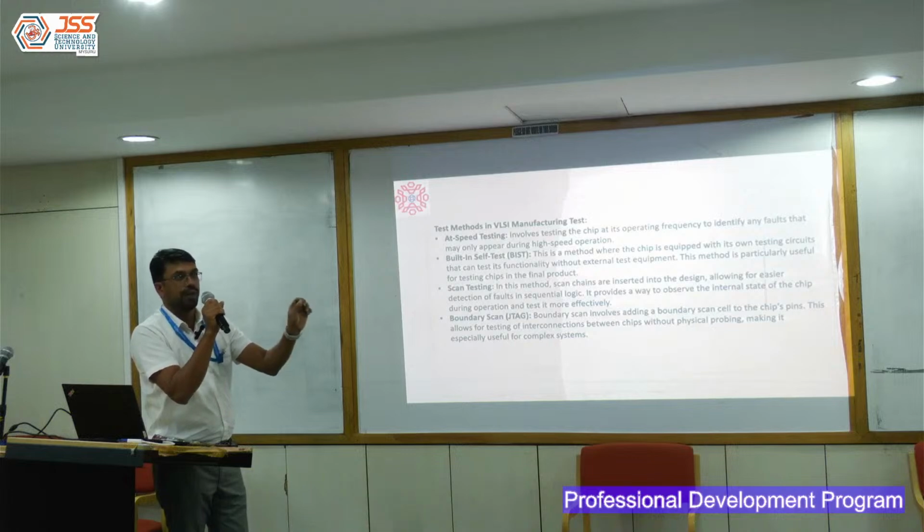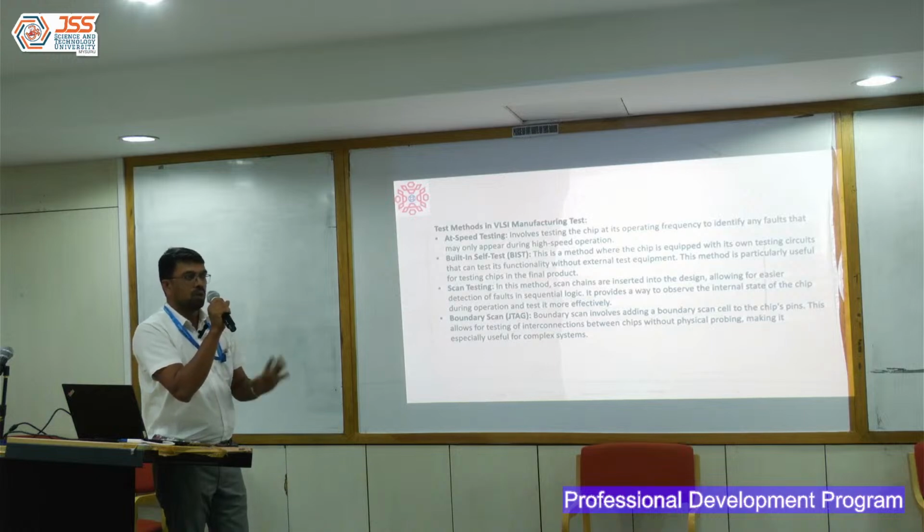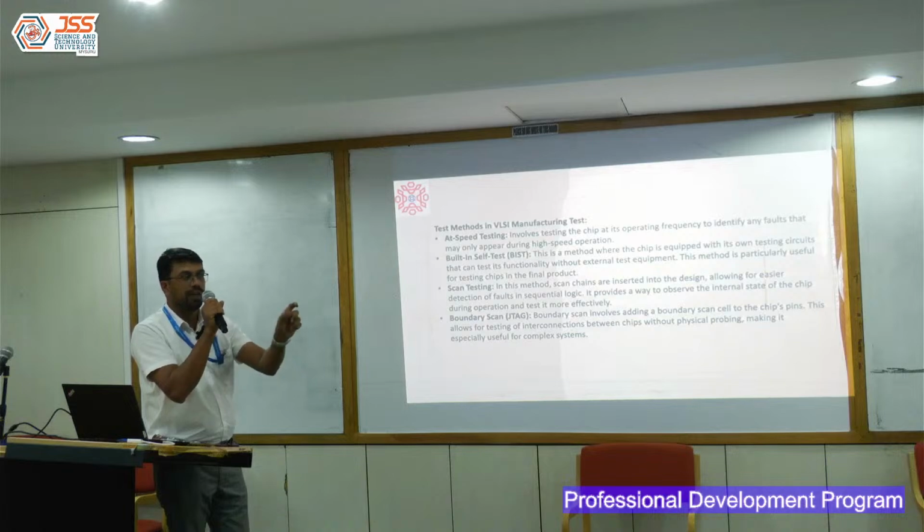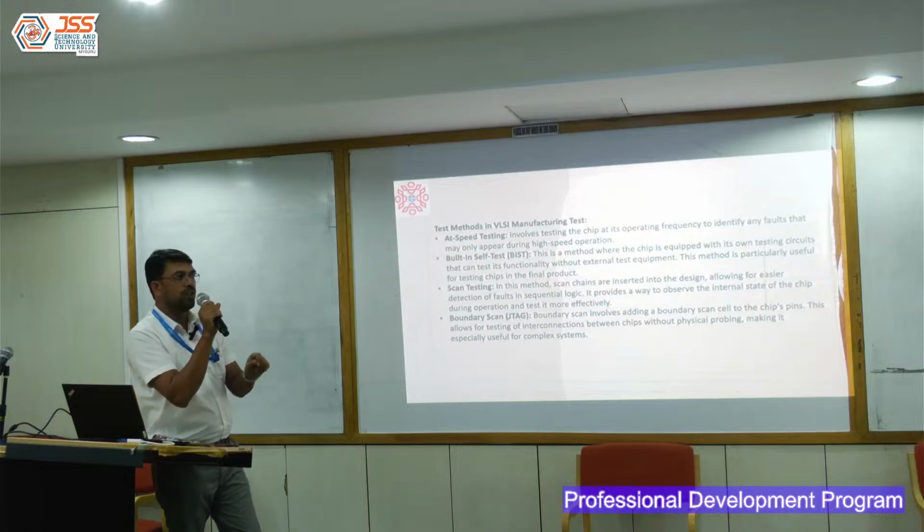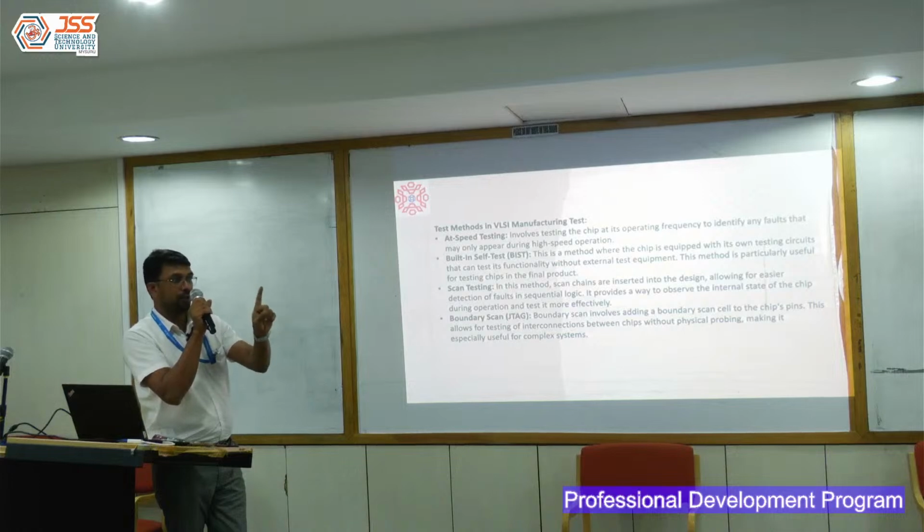If I have a setup violation, it means the clock has arrived but my data is not stable. So I can delay the clock, give that additional time for the data to settle down. Agree? But what does hold say? Hold says it's the minimum amount of time the data has to be stable after the appearance of the clock edge.